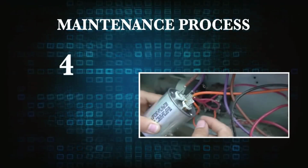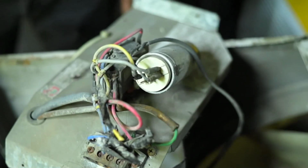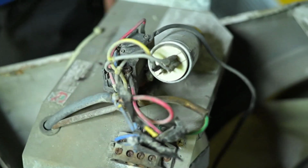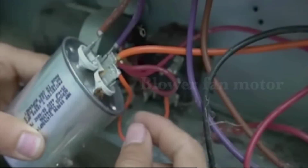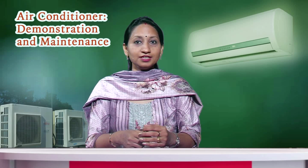Step number 4 is to check the dual run capacitor. A dual run capacitor supports 2 electric motors, the blower fan motor and the compressor motor. The most common AC problem is a faulty and weak capacitor.